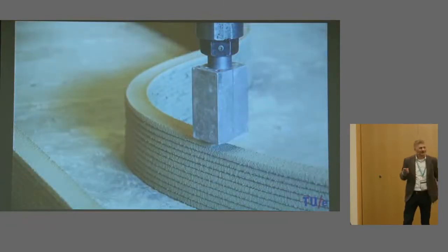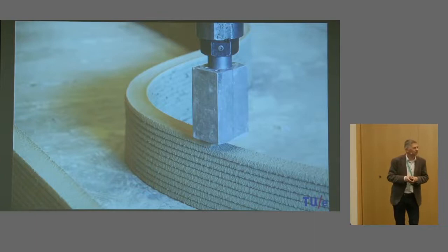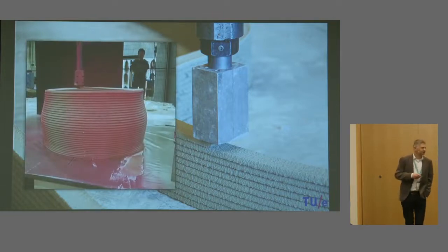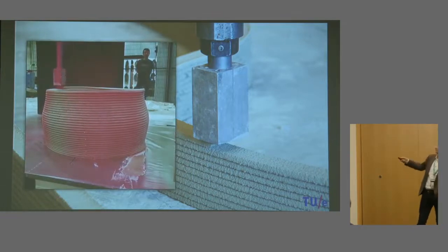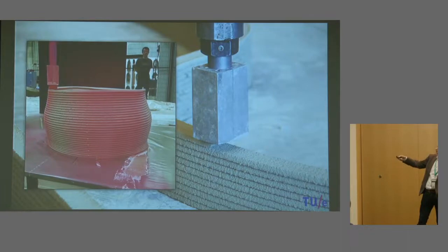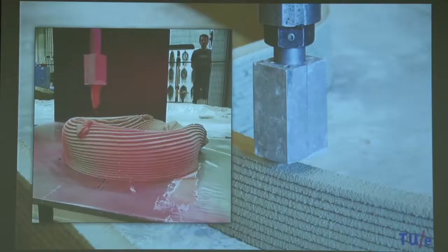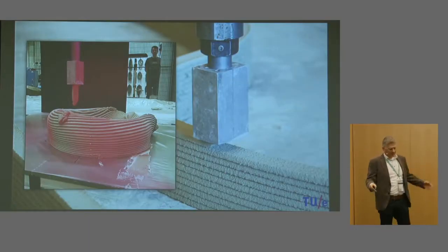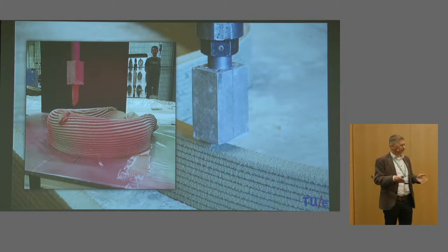If you go more in depth on the technology, where is the issue? Now, from a technological perspective, the issue is here. If you print too fast, things like this will happen. This was supposed to be just a straight column, and it simply tumbles down. As you can see, it's all fresh concrete. If I finish a column of any size, you will see bigger sizes later on, everything that I print is with fresh concrete. It's wet in wet printing, and with that comes the perfect bond between the layers.